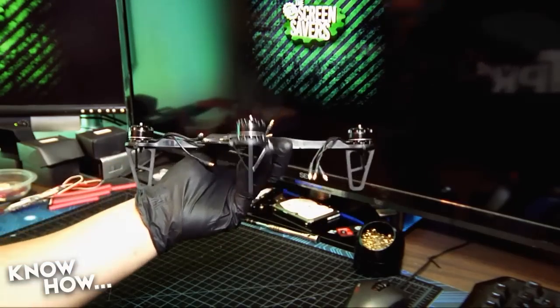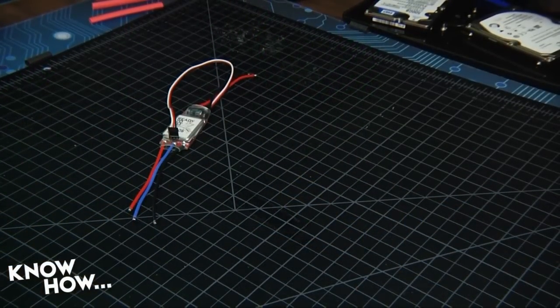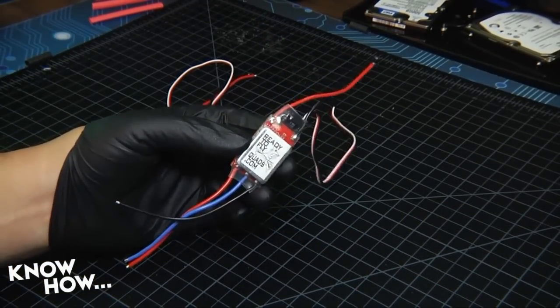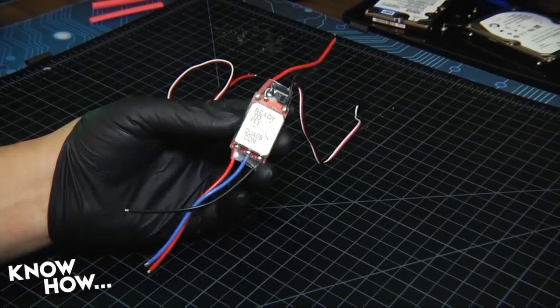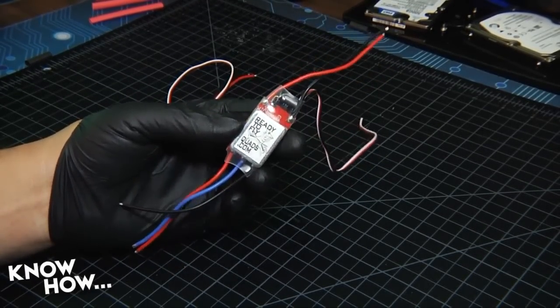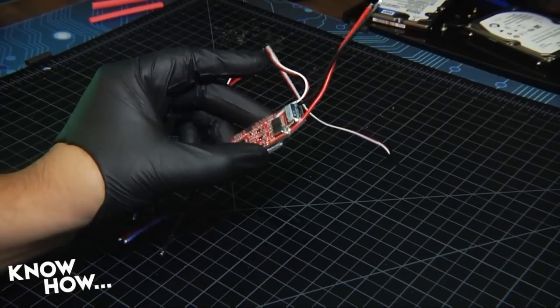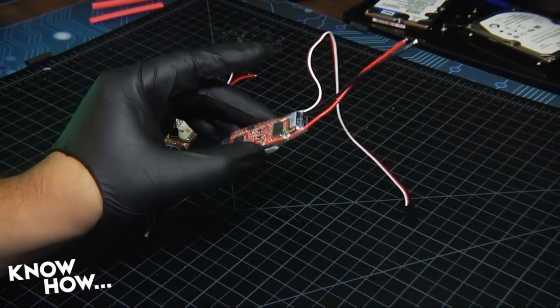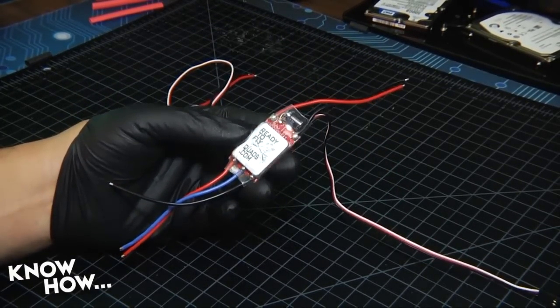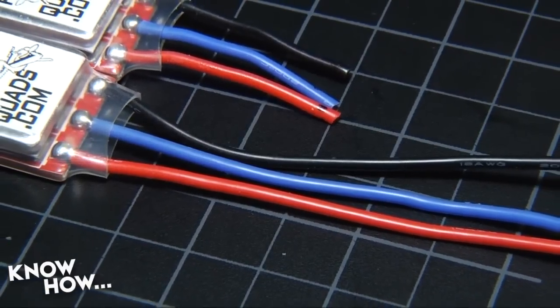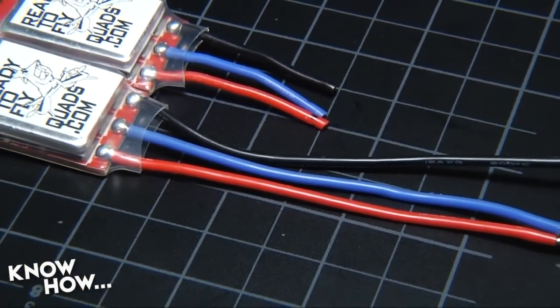We're using a set of Ready to Fly Quad Red Series 30-amp ESCs with battery eliminator circuits. We could get away with using 20 amp ESCs, but one of the things we want in the Know-How 250 is future expandability. Using 30 amp units doesn't add any weight or expense, and they can be repurposed for larger projects in the future. We're going to mount our ESCs on the lower surface of each arm.